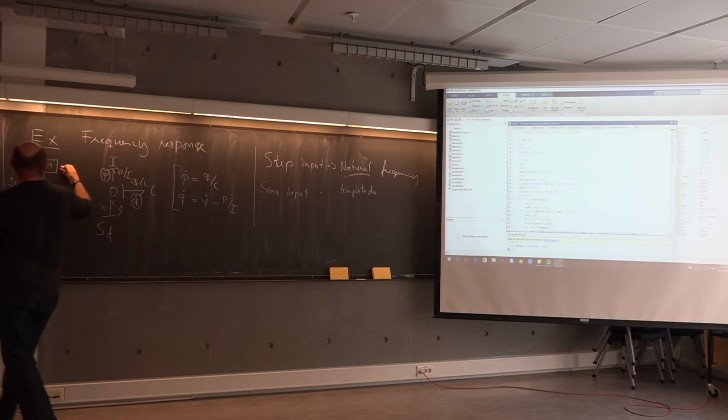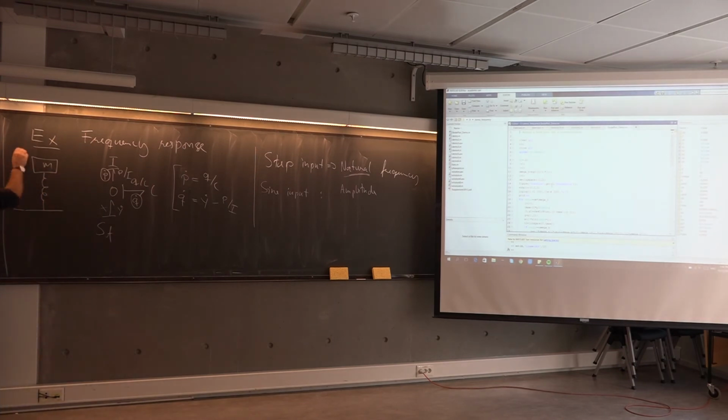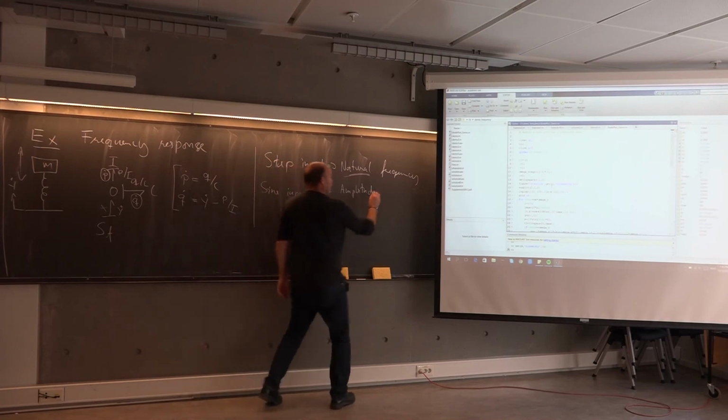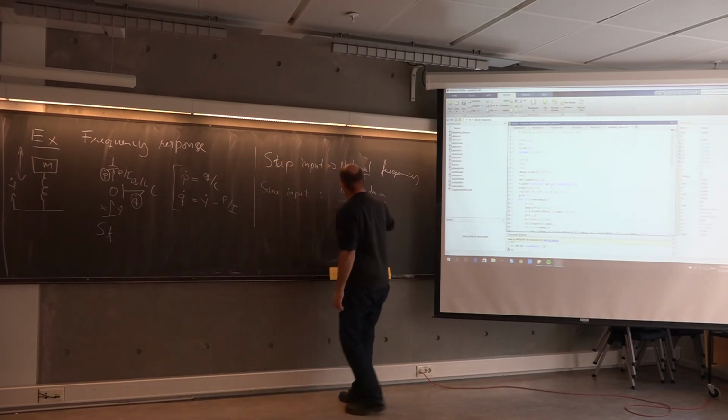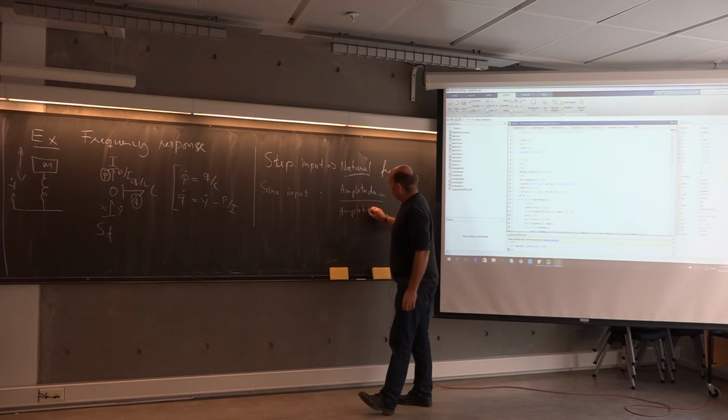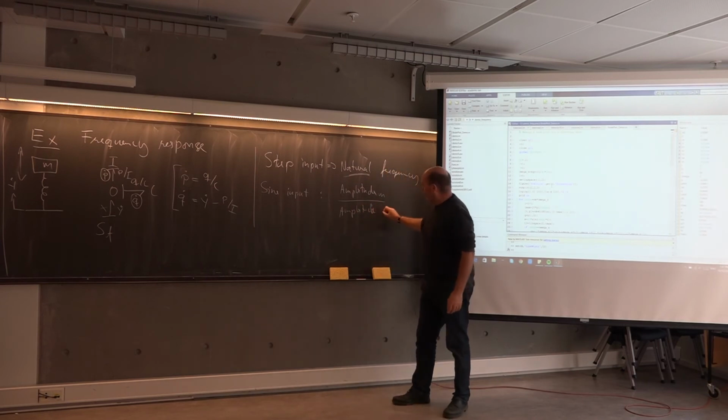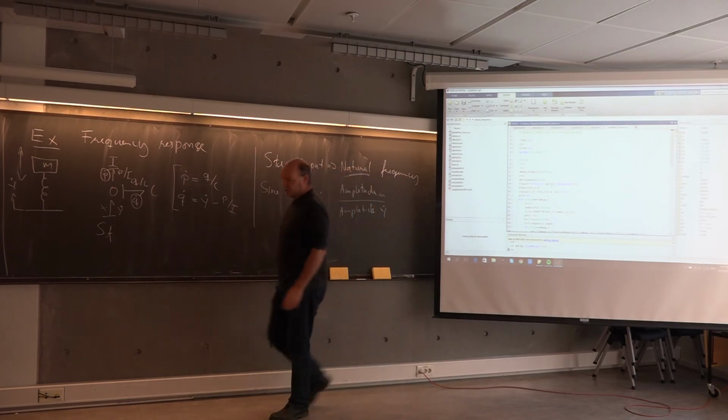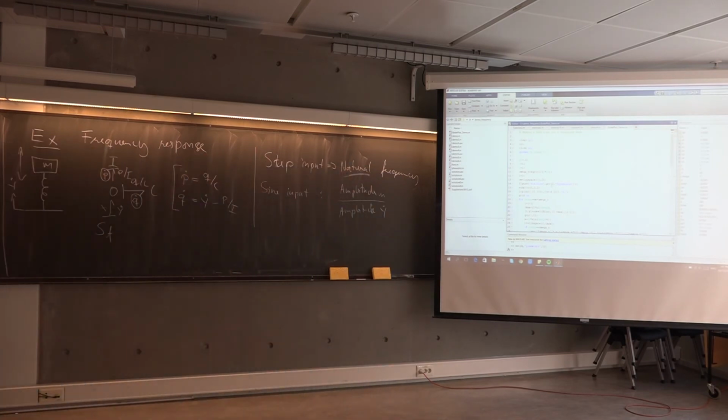And in my example here, it will be then the amplitude, the displacement here for the mass, how high will he move, divided by the amplitude of my input signal. So there we are talking about an amplification factor. If it is 1, then you send in a signal here with amplitude 1 meter, and then the system will have an amplitude of roughly the same.